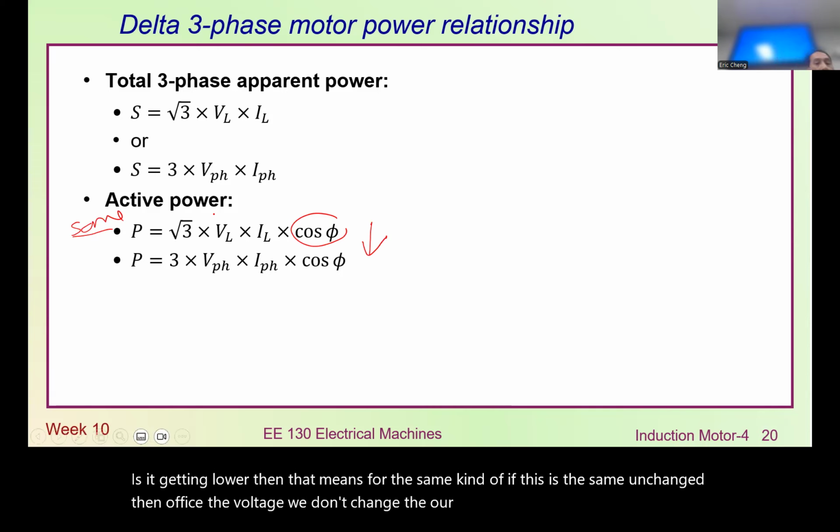Because when we measure the no load condition, the motor is rotating without any I2 current. So in theory, this resistive loss could equal the R1 resistance. However, there may be some friction and core loss that we may not have calculated. So this resistance we just bear in mind will be something related to that. So we need to use another method to calculate R1.